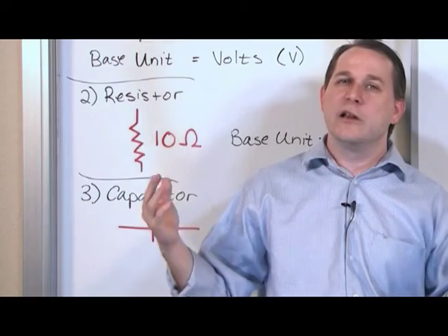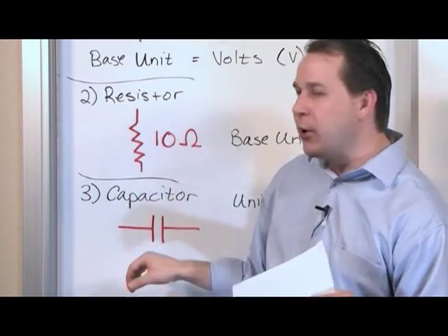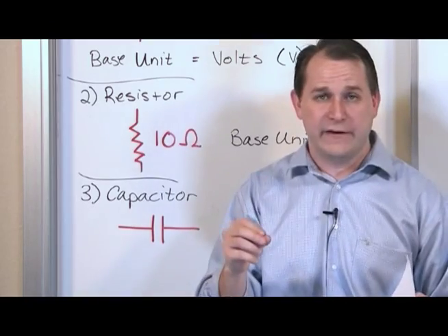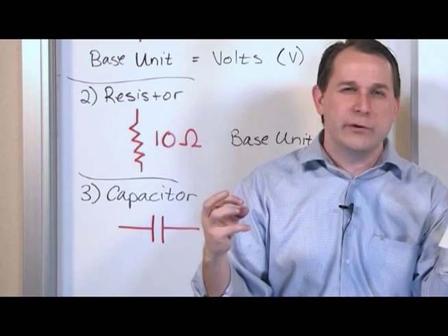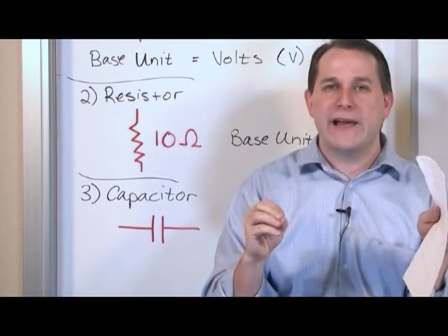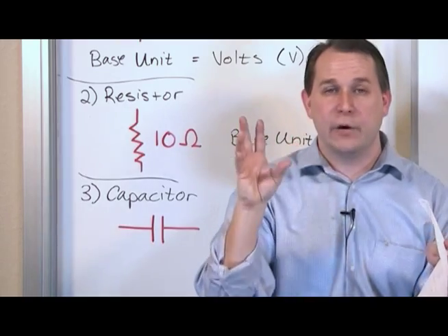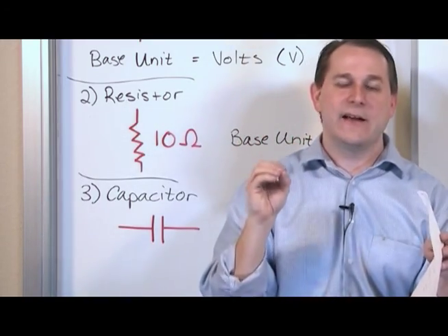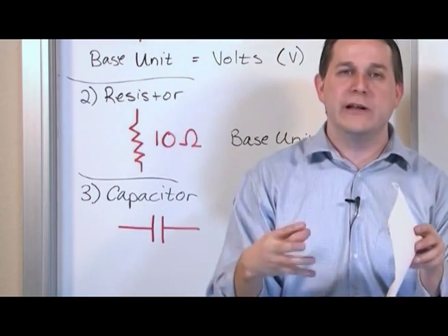What's going on there is a lot of electric charge is coming in from the battery and filling up a whole bunch of capacitors. There's a lot of capacitors in there and they're wired up together, and they're charging those capacitors, getting them really charged. And then notice on your camera, it takes a few seconds for that light to come on to tell you, all right, ready to go with the flash. That light takes time to charge up because these capacitors take time to actually accumulate this charge.